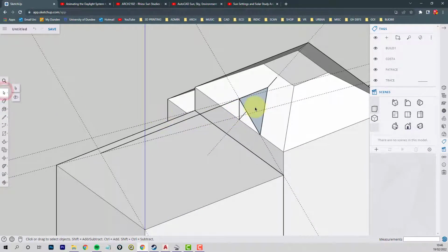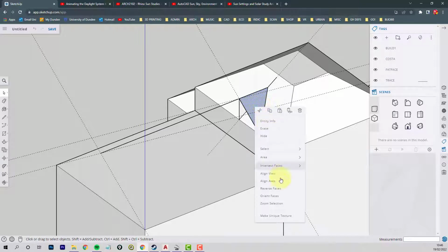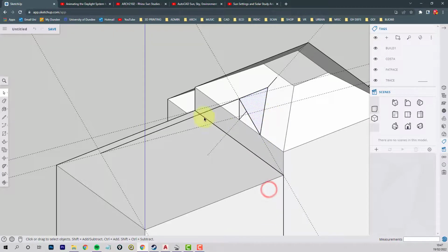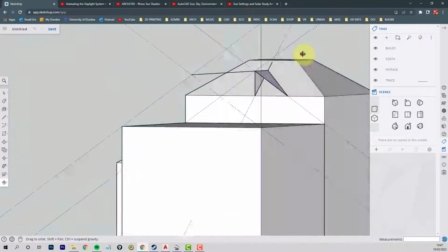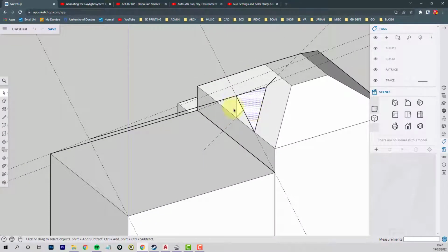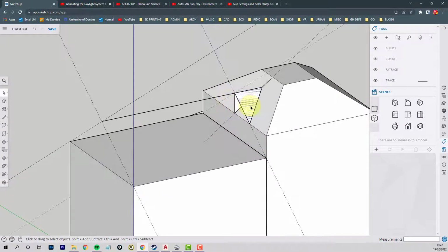So we should be able to flip that face, reverse the face, so the darker bit is on the inside. So it just kind of gives you an impression, it gives you the notification that that face is facing outwards. When it's light, it's facing outwards. When it's dark, it's facing inwards. When you do screen grabs or export PNGs and things, you don't want these dark blue bits all over the place if possible. Okay, so let's get the rest of the roof in.